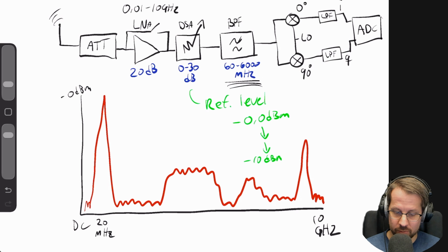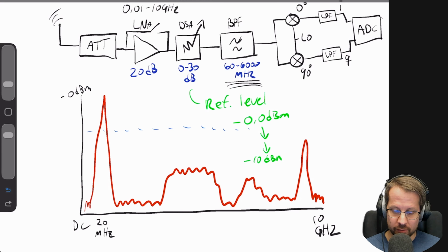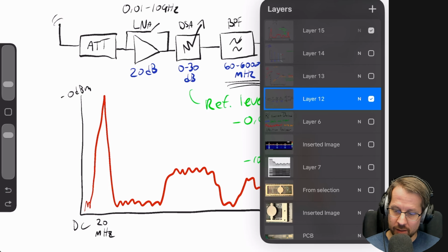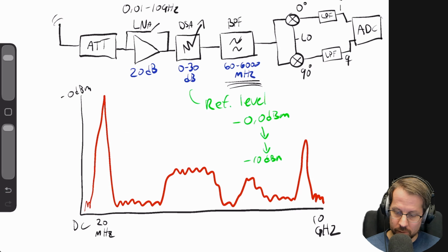So I can attenuate 20 dB, right? The other thing you can do is use filters. A filter is probably the most effective way to do it, if you really can't move away from the transmitter. So you can just remove this first.